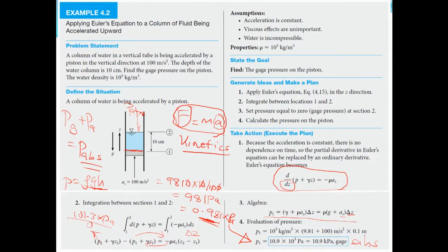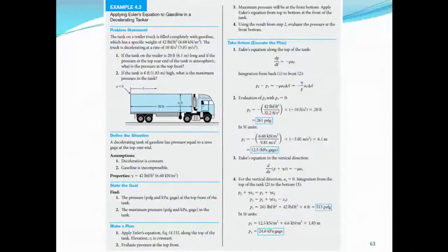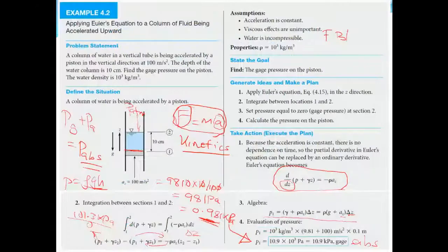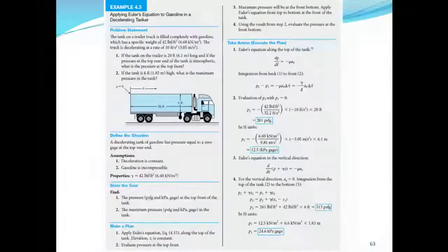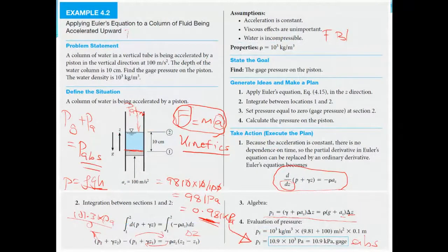You have two diagrams in dynamics: the free body diagram and the kinetic diagram. In the kinetic diagram, all you show is usually MA, that is the resultant force acting on the body and the direction of the resultant force. That constitutes the kinetic diagram. It's taking care of the force that is causing the motion.